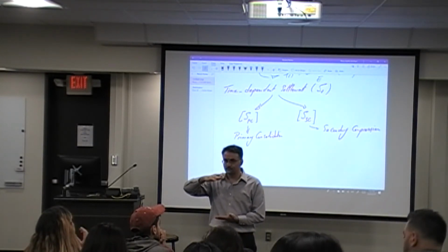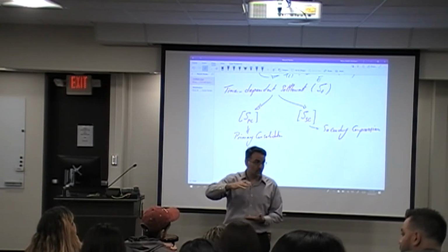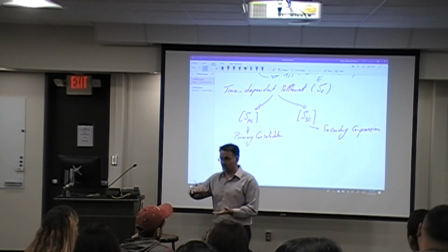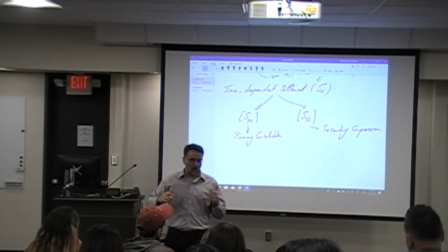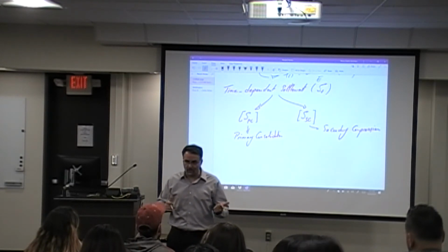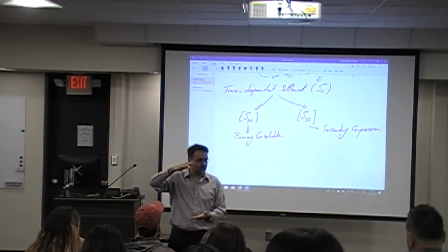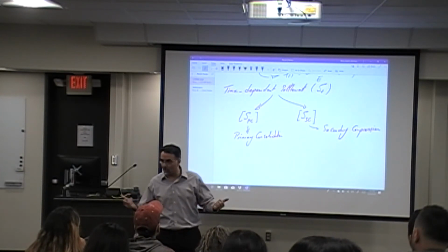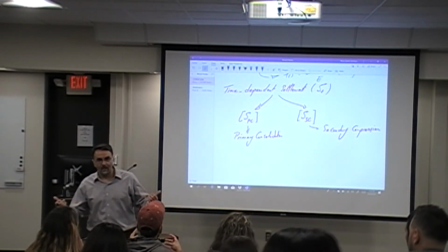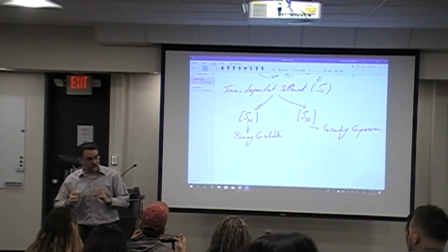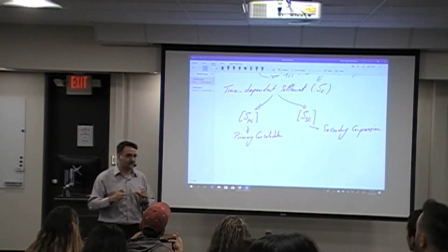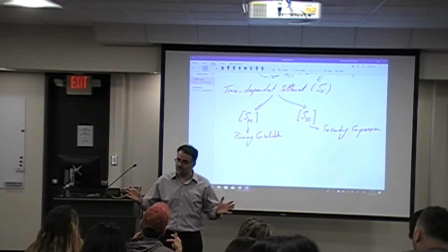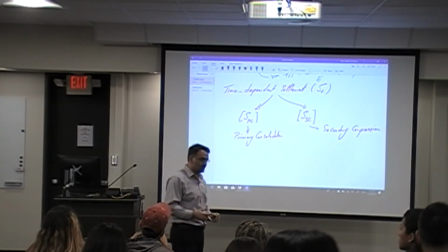All right. So let's assume I apply the load at the top of the medium. What happens? So remember what we talked about in terms of the stress transference plots, right? You had it in your lecture notes. As soon as I apply the load, because of the fact that water is incompressible, also solid grains are incompressible, what happens? All the stresses initially will be transferred to the water within the medium. And as the water moves away, or discharges, or dissipates, what happens? The water pressure goes down. Do you agree? Yes. What else happens? Now you have the transference of pore water pressure to the effective stresses, right?